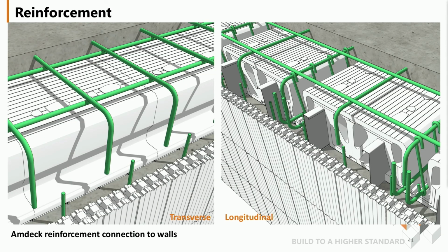The Amdeck system, like any concrete slab, would need to be tied back to the wall. This is easily done by bending the ends of the rebar either up or down into the concrete core. When your slab portion has rebar, the bent dowels would match the spacing of the rebar. When using welded wire mesh, one would need bent L-shaped pieces of rebar to be placed along the perimeter of the Amdeck at intervals as specified by the engineer.